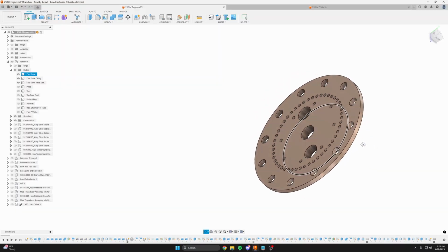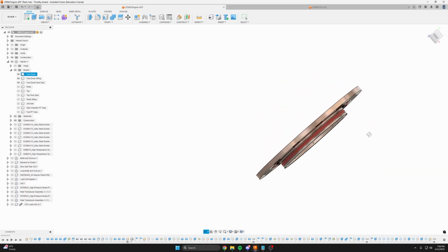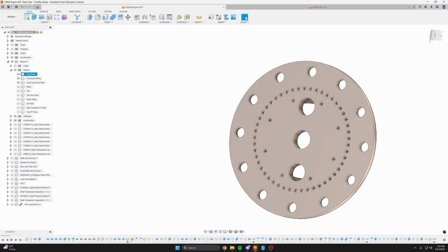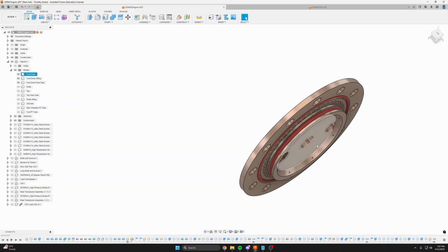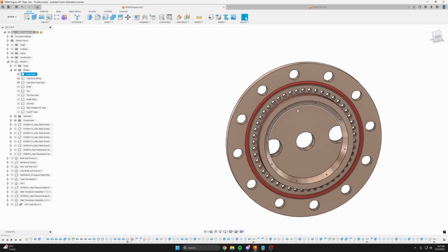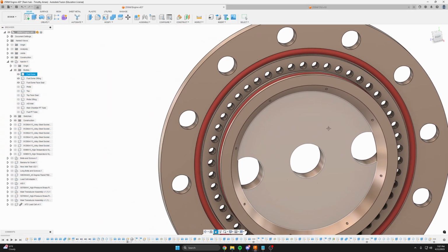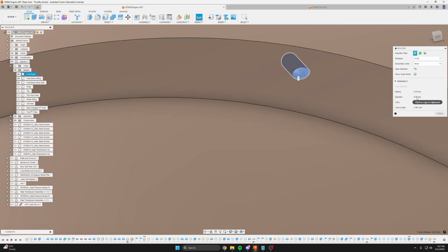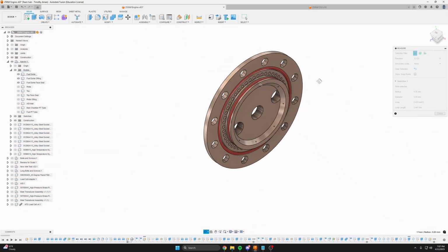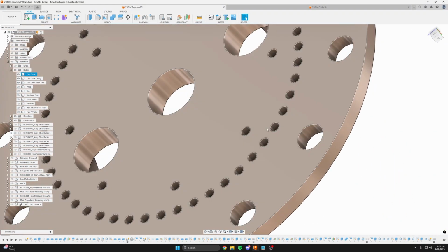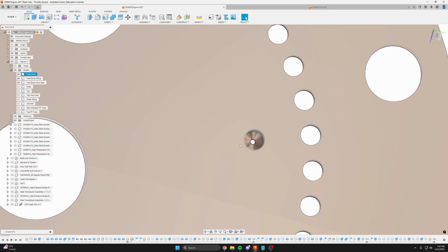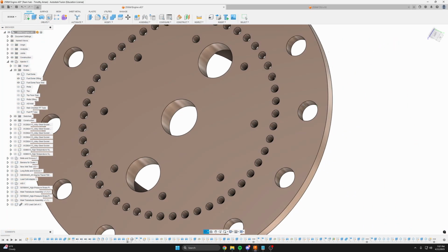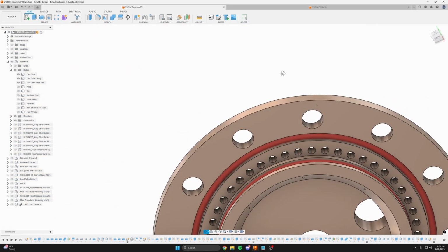This is the fuel dome part of the injector. Fuel flows through the cooling channels, flows up through these 49 holes, and then goes out through this annulus here, and also through these 8 film cooling holes. We were limited in number of holes by the diameter. You can see each of these is half a millimeter. That was about as low as we could go with the drill bits and machines we had access to. You can also see that they're countersunk at a 2 mil diameter most of the way, so you just have to peck through that last little bit at half a millimeter diameter. I would recommend doing that if you're doing very small film cooling holes.